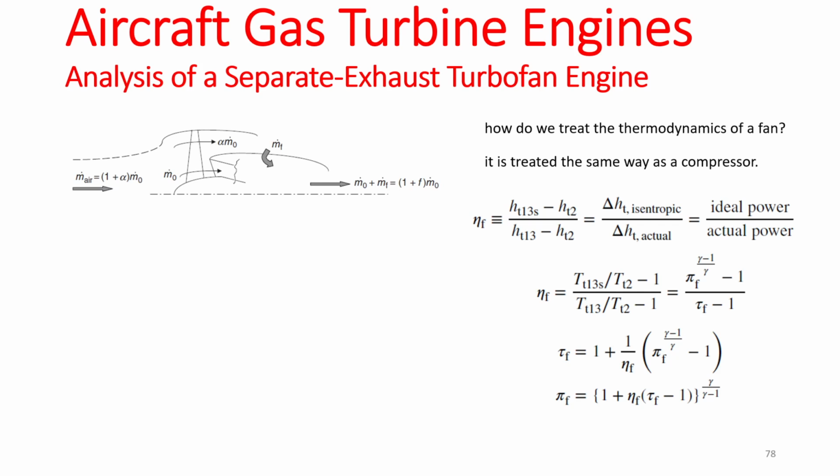I remember before we were saying that the turbine power is always equal to the compressor power times an efficiency factor. Okay, so what is added here? The fan. The fan, okay, so the turbine power is equal to the compressor power plus the fan power, right? That should be the conservation of energy, right? But how can we calculate the turbine power by itself?